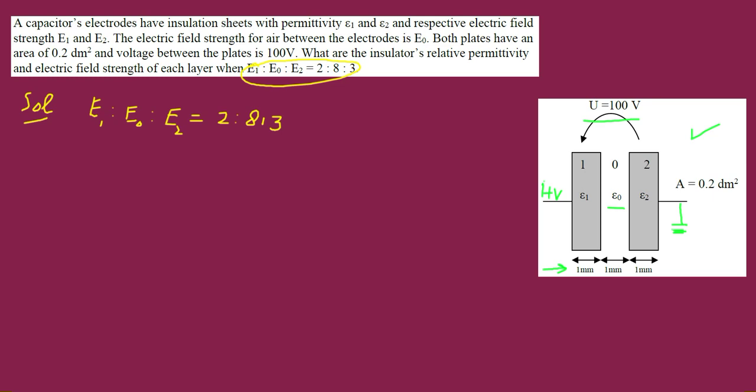Now, in this problem, as we can see, the voltage rises from right to left, and this applied voltage, which is 100 volt, is being dropped across different layers of insulation. So this type of combination of insulation layers is considered a series combination of insulations. With the applied voltage as shown, the electric field will be from high potential to low potential.